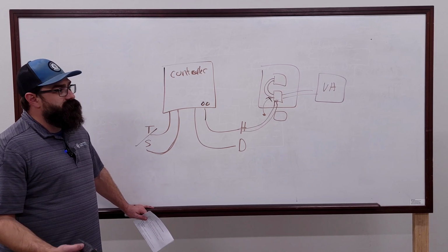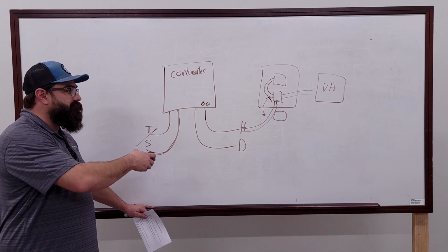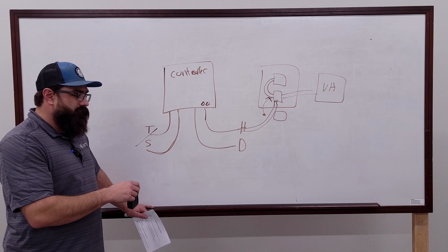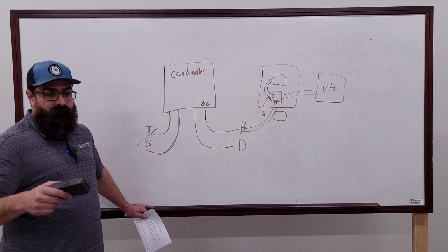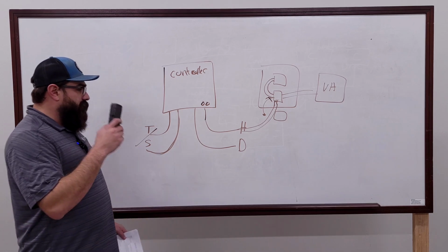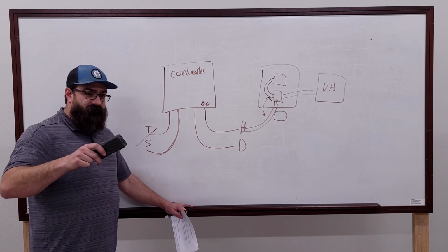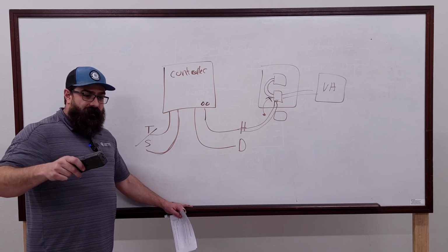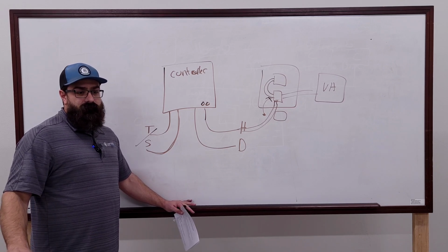And then a lot of times, I don't even necessarily have to look at the controller to tell you where it should be. Like Distech, it's always going to be a particular output, right? If you're a staged heat, it's outputs 1, 2, and 3. Output 4 is fan. Analog is always analogs 5 or 6. Every time.